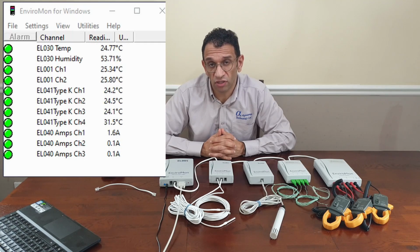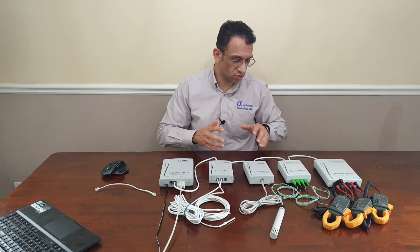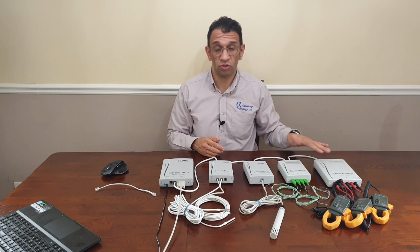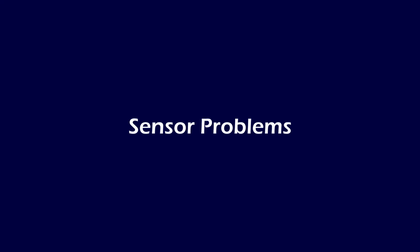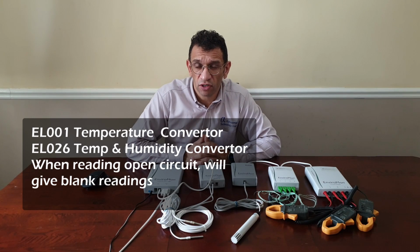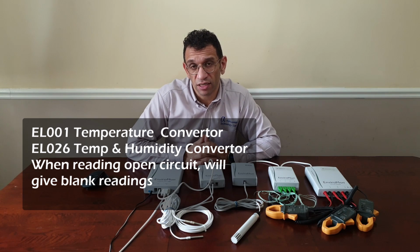So now the fourth converter appeared. As you can see, when there was a problem with the converter cable between the second and the third one, it also knocked out the fourth one. Depending on the converter that you're using, a faulty sensor could give blank readings. This particularly happens with the EL001 converter and the EL026 temperature and humidity converter. When they read open circuit, they will give blank readings.